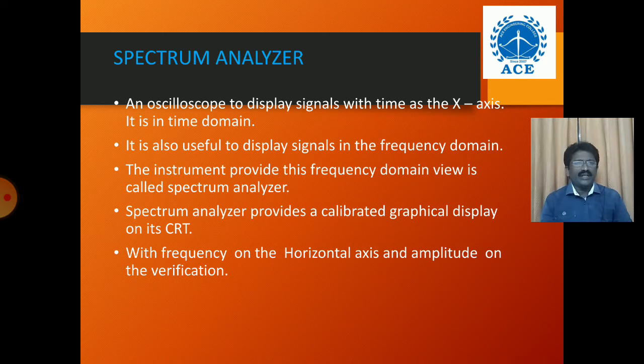The output of the active filter you pass to a driven amplifier, with the help of which you can vary the output of the Q active filter. Finally, you can see the output of the frequency selective wave analyzer in the meter, from 20 Hz to 20 kHz. So this is the frequency selective wave analyzer.